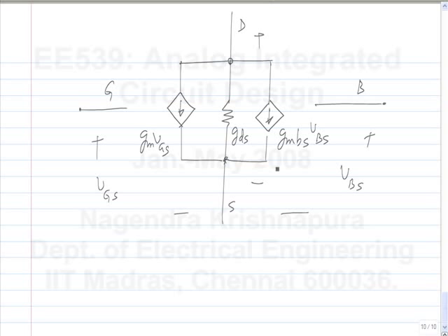And the increment between these two is VDS, okay. So, this is a DC or the low frequency small signal model, because we have not considered any capacitances or charge storage effects so far. Any questions on this?